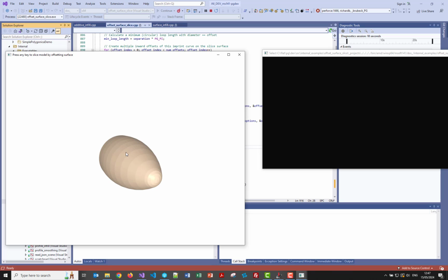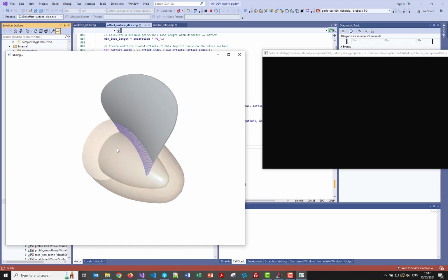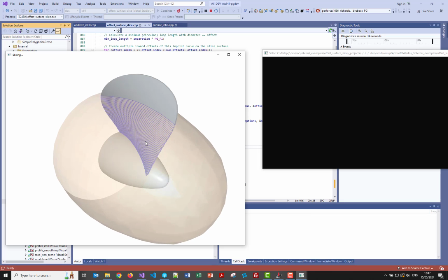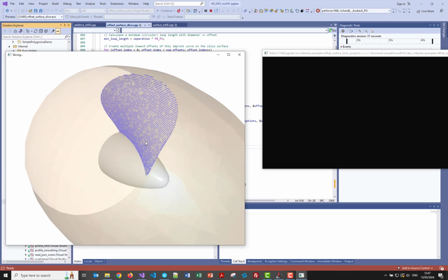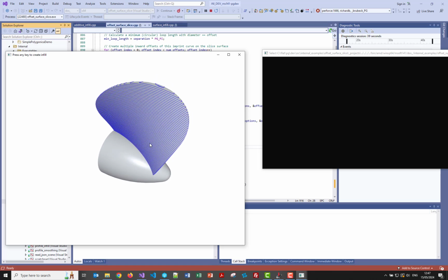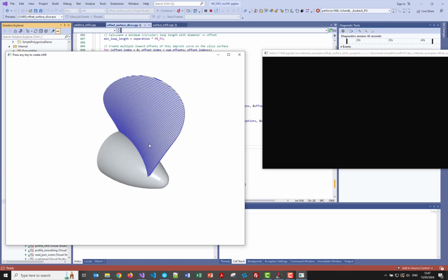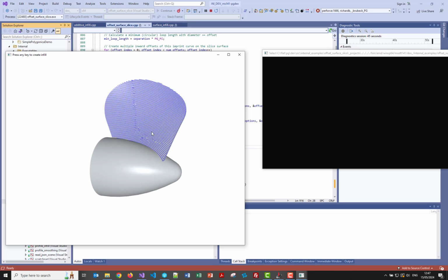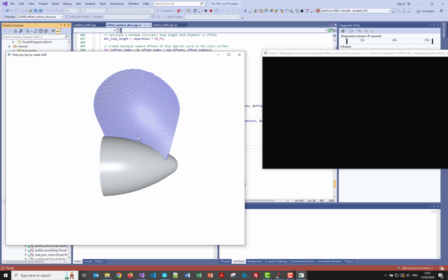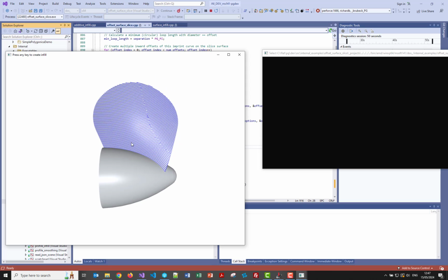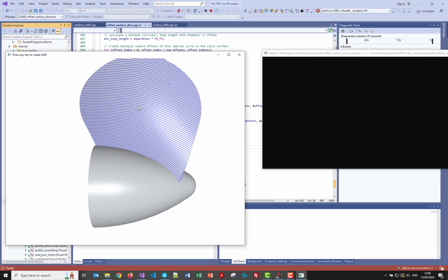Okay, so first of all, the idea here is we're going to use offsetting to create the intersection surface. Here's the outside of the engine, and then we double click, and it's doing successive offsets and creating the intersection curves from them. I'm not sure this is how you would do it in real life. It's more a proof of concept. Apologies for the graphics issues there. But that's created a nice set of curves. You could just use a radial one rather than offsetting this surface, but there are possibly cases where offsetting this surface would be useful.